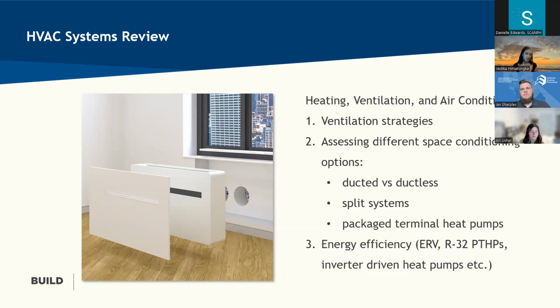And of course, after analyzing the plan sets even further and determining which one of these is the best fit, finally, we have a look at ways in which we can make the system most energy efficient, and that involves providing recommendations like incorporating ERVs, switching from regular PTHP to R32 PTHP, increasing heat pump efficiencies, or switching to an inverter-driven heat pump.